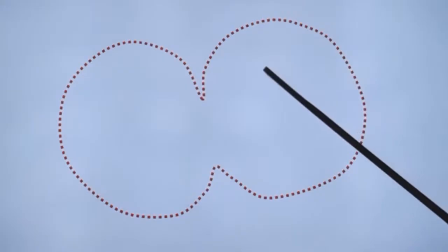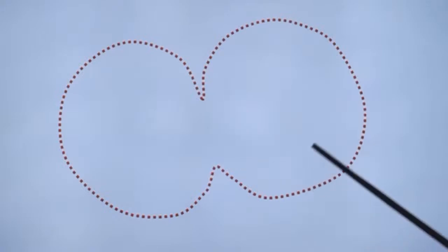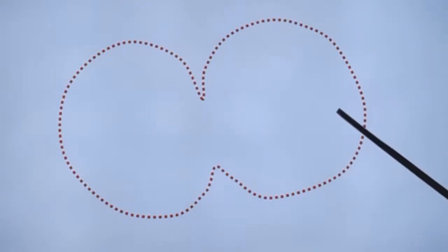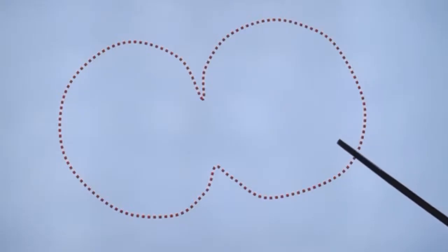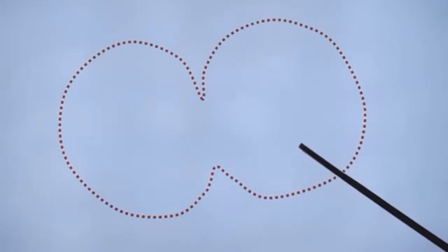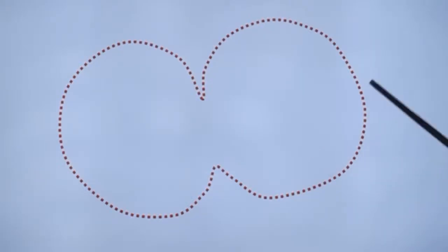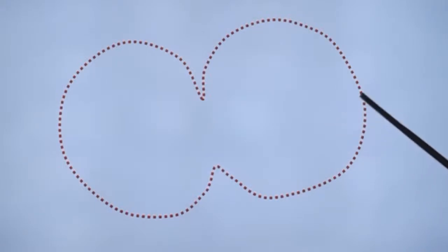Of course, a single J-pole antenna is not the ideal one for satellite communication because this will not have a high gain, and being omnidirectional, the whole of the radio frequency which you radiate from the J-pole will not reach the satellite. Only a small fraction will reach the satellite. Unlike in case of a Yagi antenna, which has a high front to back ratio and directivity, most of the signals would reach the satellite. While here, as the radiation pattern is omnidirectional, only a small portion will reach the satellite.